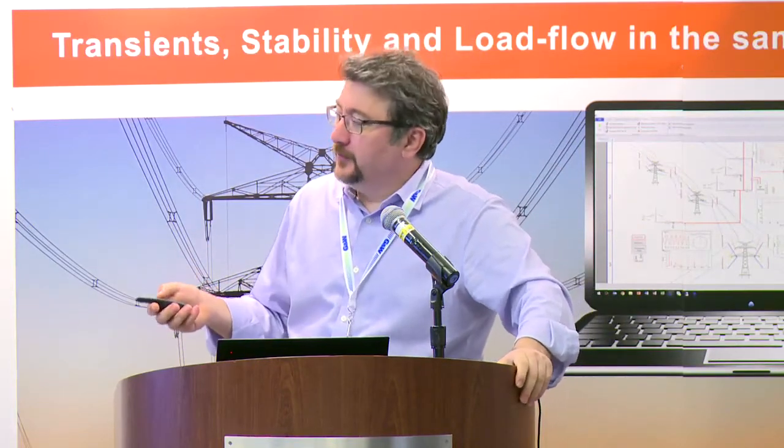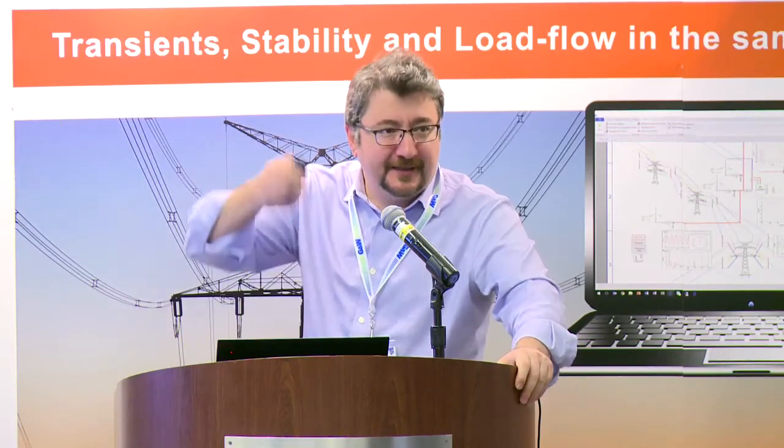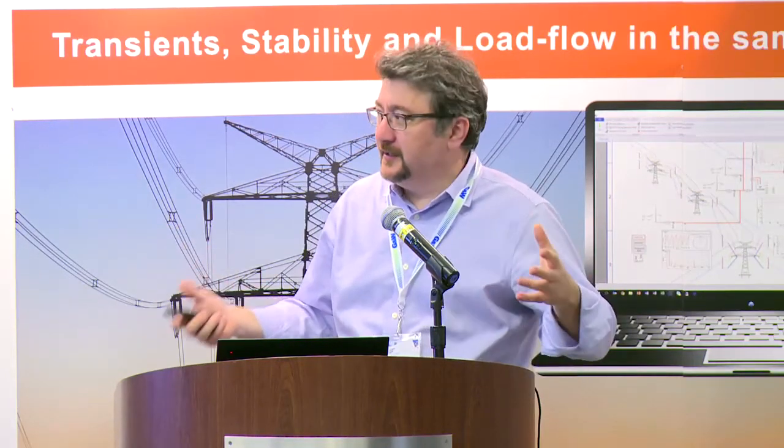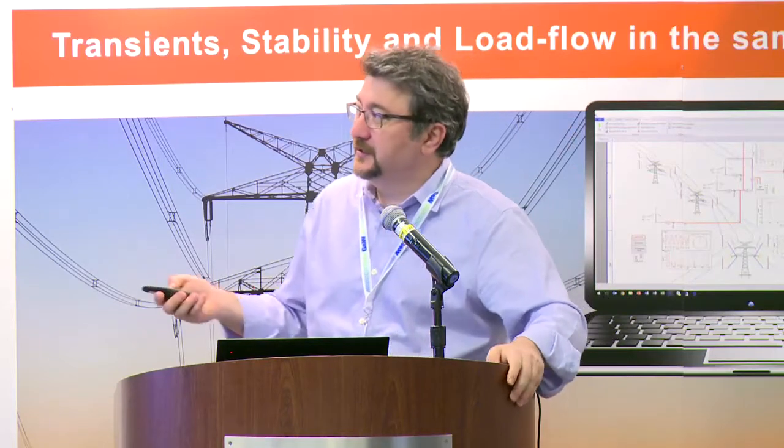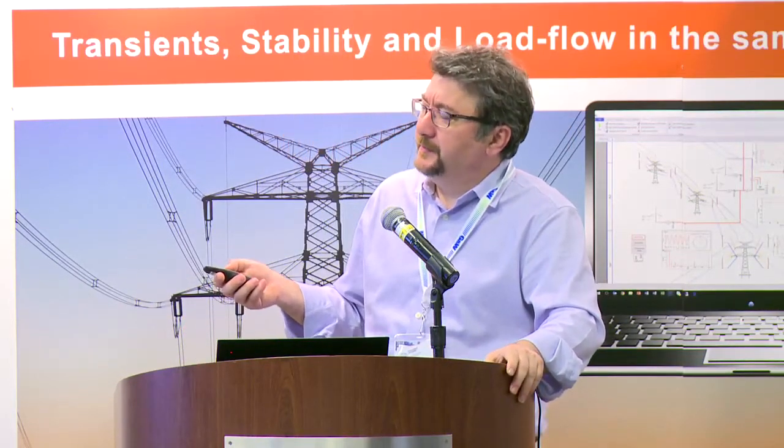So in those cases, of course, one solution is you reduce the time step. So this is the number one solution, for example. Okay, the model is good, passive and whatever, but your state space parameters are not balanced. So what you do is you reduce the time step, you reduce your numerical errors, you reduce your interpolation errors or whatever.